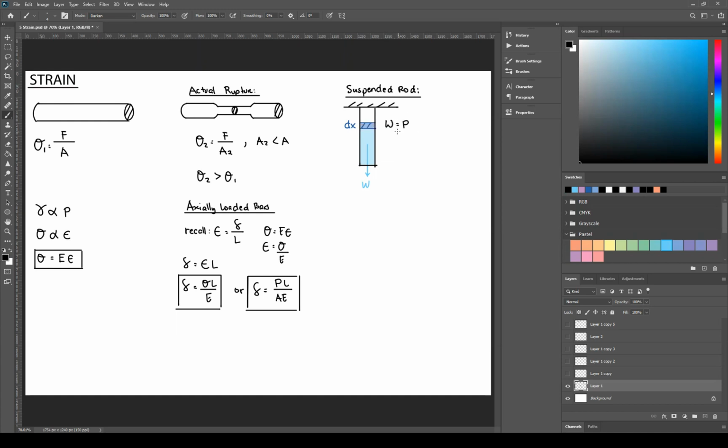To create an equation for weight, recall that density is simply mass over volume, and then mass is just density times volume. If I multiply everything by gravity, g, you'll get mg equals rho gV. mg is weight, rho gV. Therefore, your actual force is also equal to rho gV.